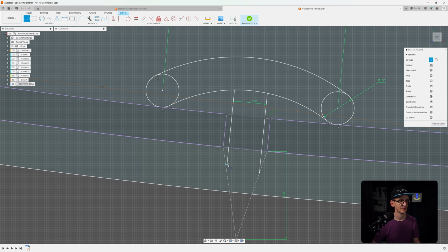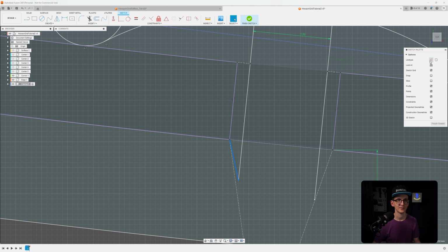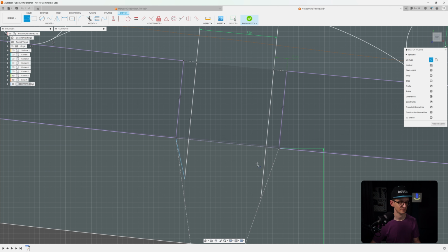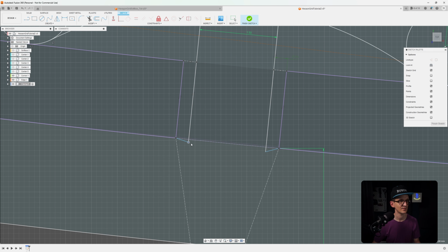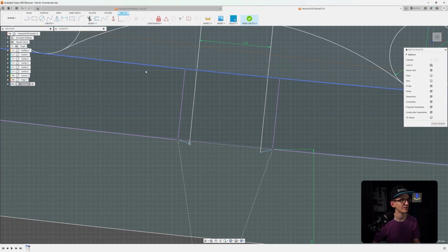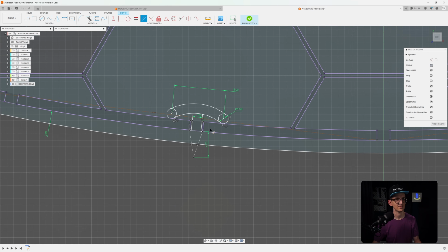And then as a last step, not as a construction line, sorry. So as a normal line, we deselect construction, we select this and go here. Actually, I don't know exactly what shape it should have. I guess it doesn't really matter. So we can have this actually be parallel to those lines as well. And now we have a perfectly defined shape. That's exactly what we want.